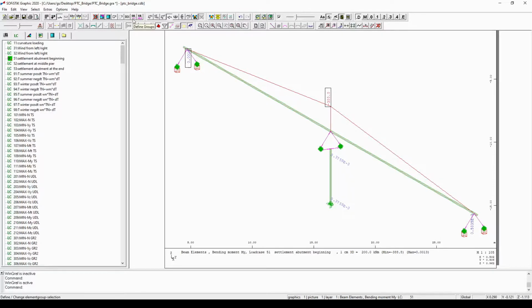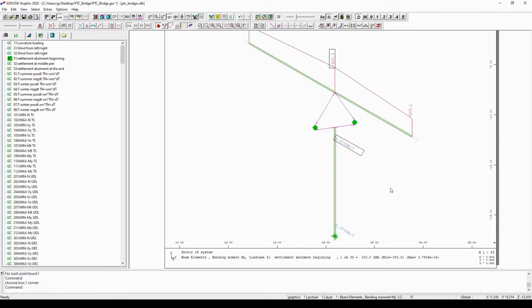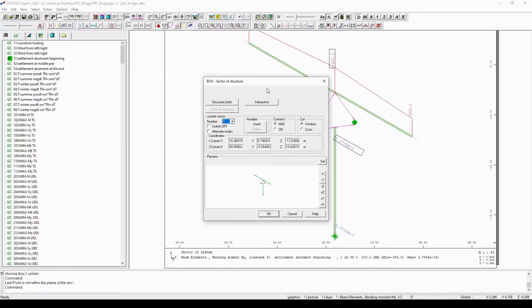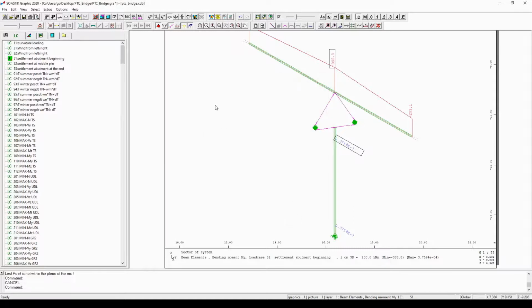Next to the Group All and Group buttons, you can find this Change Box button. When you have a box view defined already, you can set the properties of this view box with this button. Let me show you. For example, if I click on the box and create a box view, now I can click on this Change Box button and I will be directed into this dialog box, in which we can see all the information regarding this view, and if you want, you can set any properties of this view. However, we are not going to do that. I just wanted to show you that it is possible, so I will simply click on the Cancel button